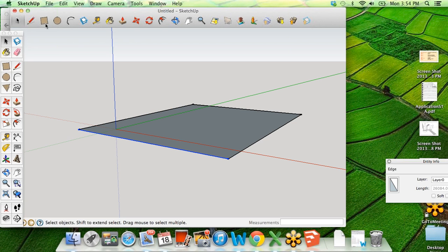All right. I'm going to go back to this line tool just to show you these different markings. If you hover your mouse over, if you want to draw another line or a rectangle, SketchUp tells you if it's an endpoint, which is green. If your point is on the edge of a surface, on that line, it will be red. And when it's at the midpoint, or halfway down that line, it becomes that cyan blue. It's just letting you know when you're marking.